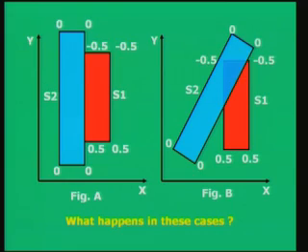If you split the rectangle which is surface S1 into 2 parts, you can draw the back side of S1 first, and then the blue one, and then the remaining part of S1. That will be the order which you will get in this particular case. I repeat again, if you split S1 into 2 parts, the back side of S1 first, then the S2 inclined blue surface, and then the front remaining part of S1 is what you can draw, and that will be the correct ordering and the correct impression of this figure. So, you can only implement that by splitting.